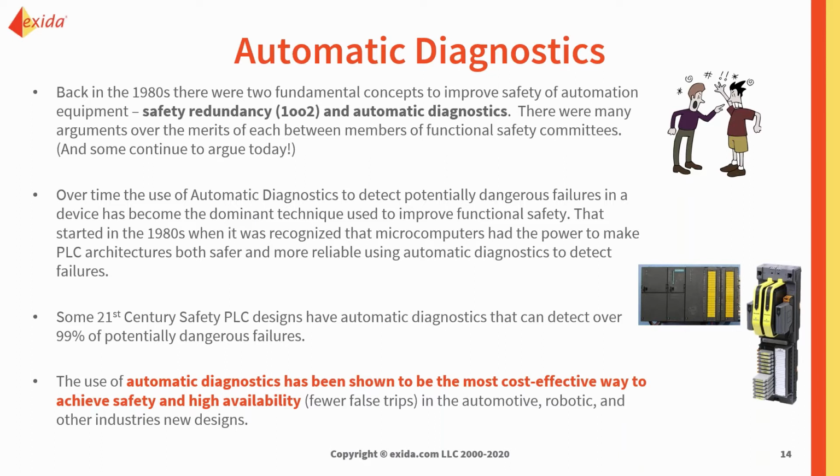Automatic diagnostics were definitely in the picture when IEC 61508 was being developed. And then over time, they've been used more and more to detect potentially dangerous failures and have really become the dominant technique used to improve functional safety.